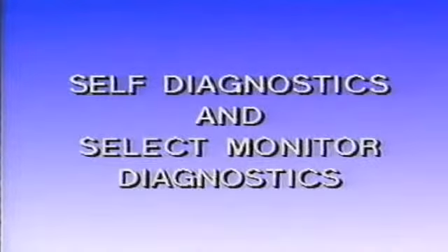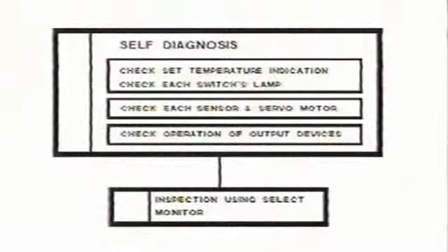The SVX Auto HVAC system has two options for diagnosis: a self-diagnostics program built into the system and the Subaru Select Monitor. Self-diagnostics and the Select Monitor should be used together for thorough and accurate diagnosis. It is important to understand that diagnostics can only lead to the general area at fault. Proper troubleshooting procedures are required to determine the exact failure.